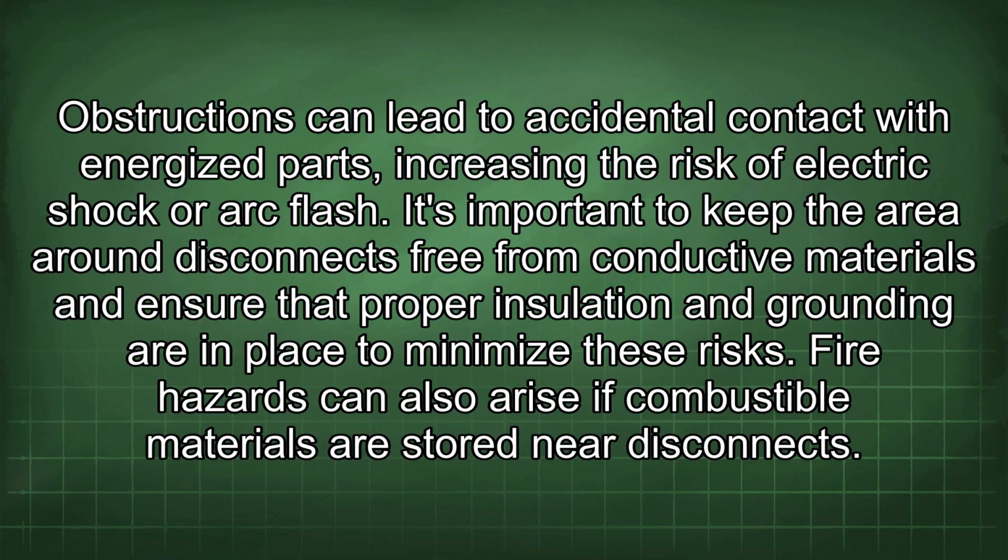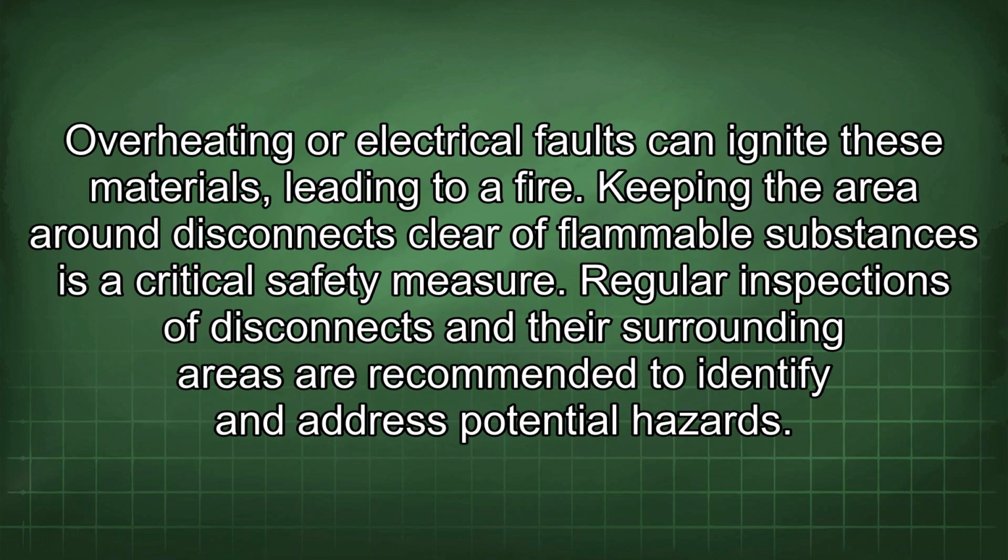Fire hazards can also arise if combustible materials are stored near disconnects. Overheating or electrical faults can ignite these materials, leading to a fire. Keeping the area around disconnects clear of flammable substances is a critical safety measure.